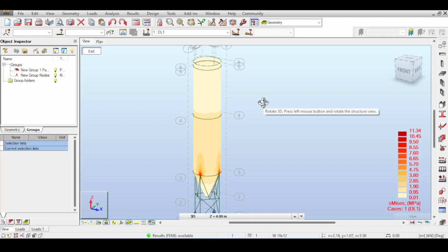So I know my 1 inch seems to be an over design, but I just want to hammer home the point that, yes, it's an over design right now, but I need it to withstand also handling and transportation loads, also impact loads, especially in transportation. Because if I make a steel sheet of, I don't know, 5 millimeters, it will bend and dent and have all kinds of problems when I transport this.